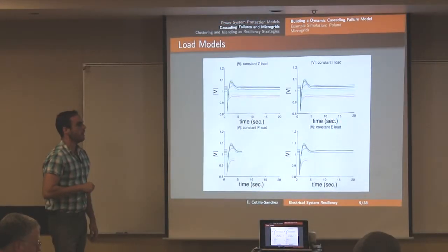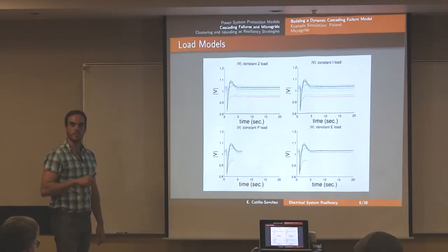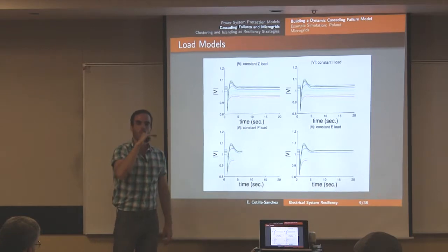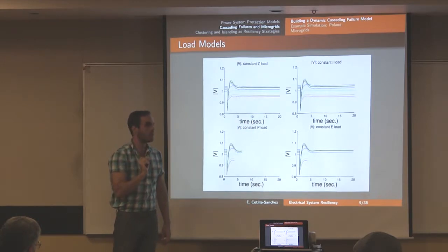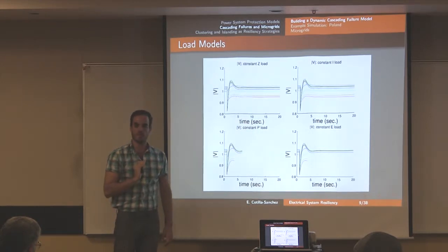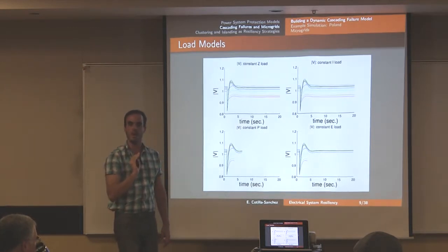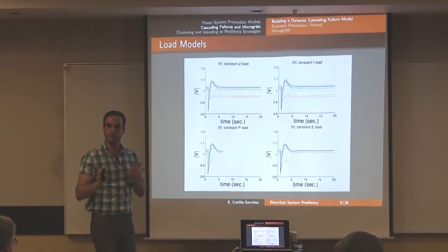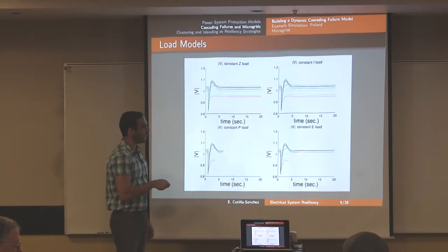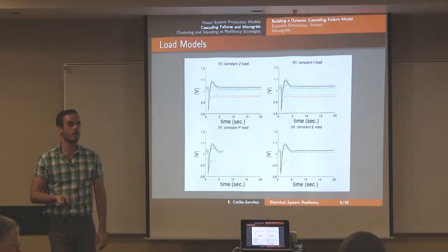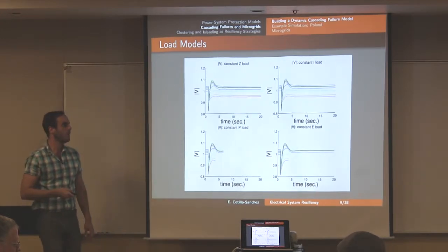If we have an exponential profile for the voltage, one of the things we did was to ask, okay, you might have constant power, but how about adding some exponential decay so that when the voltage goes down, we remove a little bit of that load, just including some exponential constant. If we add a little of that exponential behavior, it smooths out that function, and our equations and Jacobians can find a solution. Then one of the islands actually converged, but not the other one. The other one still was a solution where we were not able to find any physics that would agree with it.